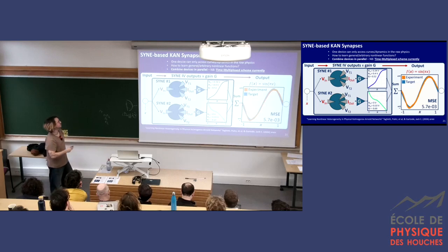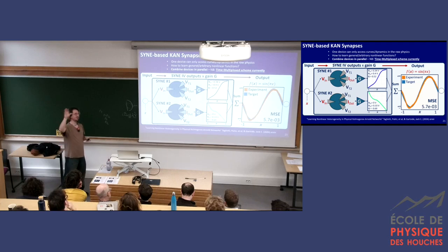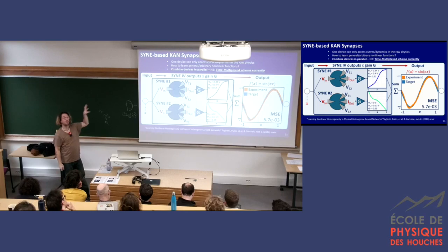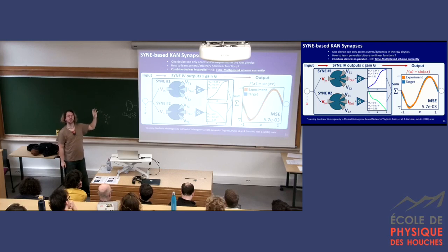So I just want to point out really clearly here, we've got a chip with 20 or 30 of these devices, but at the moment, one of them is wired up. So the guy in Milan who made these things was moving to Turin. All his students and postdocs had stopped. So I had to go out to Milan, wire bond these things up, hook it up to the internet. So I've been running it remotely. But the next step, and we're working on these now, is putting more of these together into a circuit. But right now, everything that I'm going to show you is one device time multiplexed into a network.